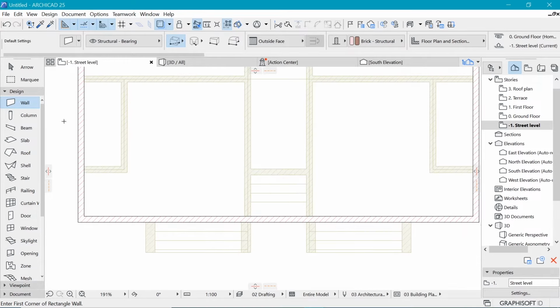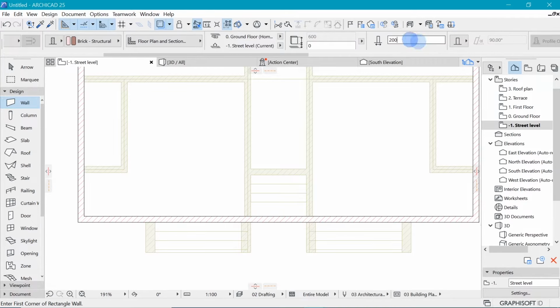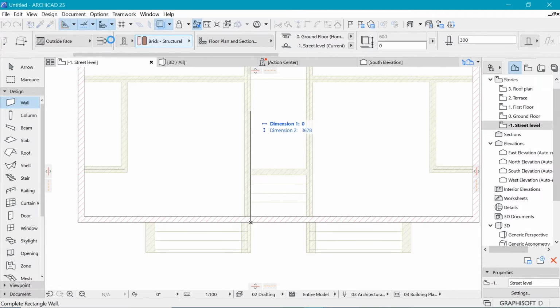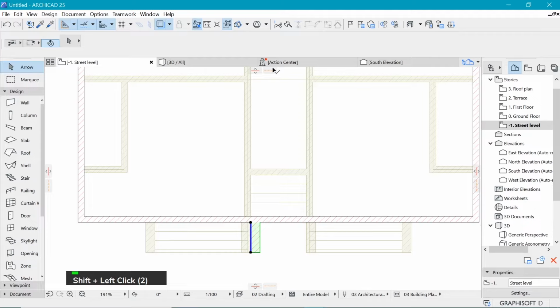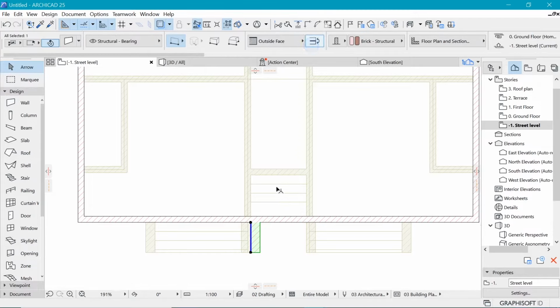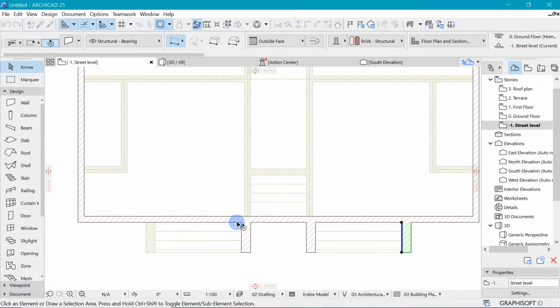And as well, let's not forget to draw the 300mm thick walls. So I'm going to make my walls 300 here. Make sure that I change from this to the single wall, and I can see that this has been drawn on the wrong side, so I will flip that here. So there we are. Make a copy and put it here, flip that such that we still have this on the same line, and then we can make a copy here and a copy there,